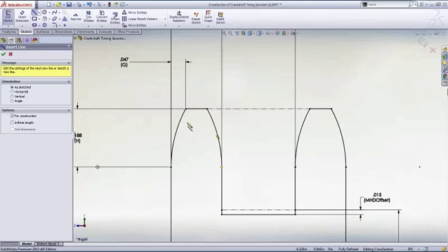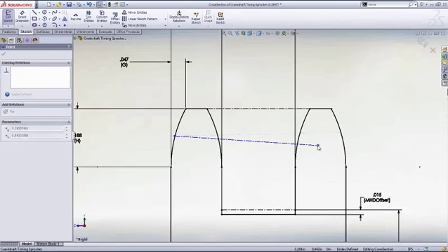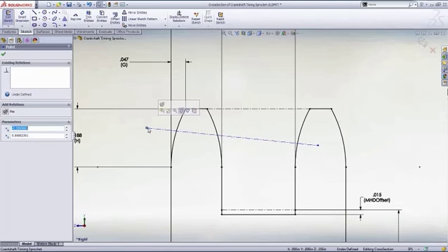This might be trying to freehand close to some existing geometry like here, or working in a fairly congested part of the sketch. Well, there's a little trick to temporarily turn off the automatic creation of sketch relations. Just press the Control key while sketching and you'll notice the little yellow icon next to your cursor disappears. Now, when I sketch this line, no relationships are added. I can see this when I try to move the line afterwards.